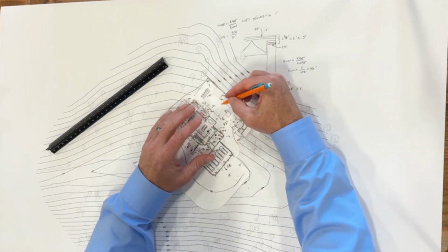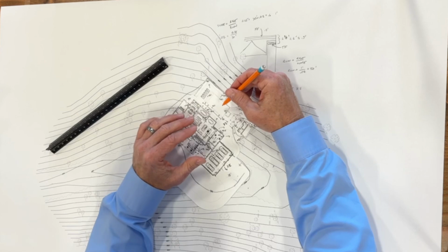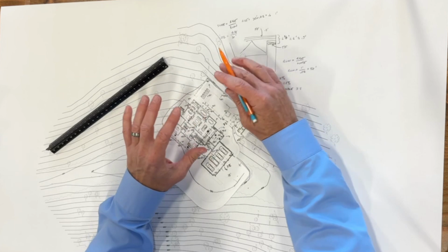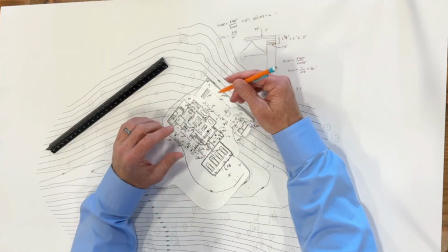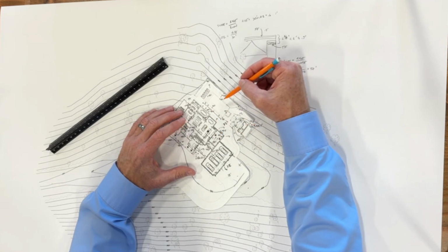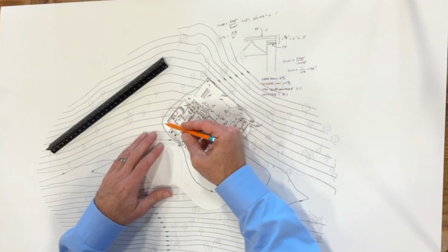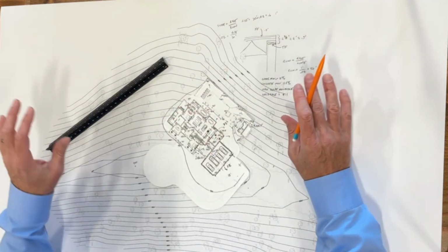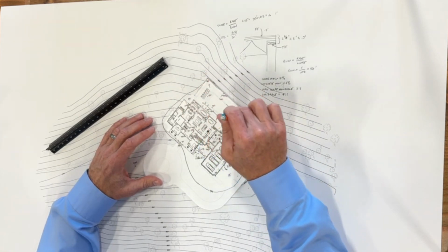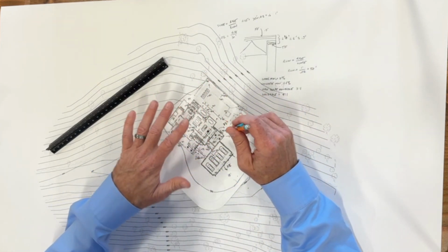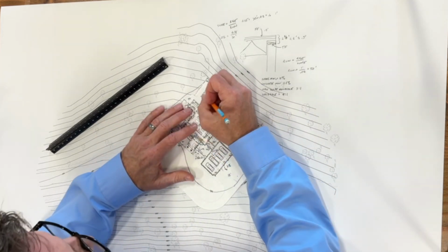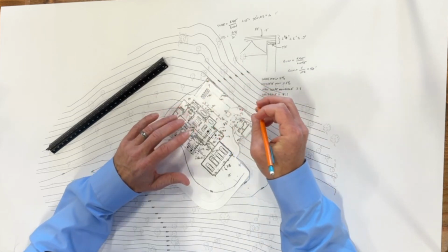Now, notice how flat this is, right? If this is not done correctly and we don't allow for all these little 6-inch drops, there will be water hanging in all these places. So it is actually harder to do this spot where it's flat, because you've got to make sure that drainage is always working. This is way harder than anything over here, because this is just going to shed off like crazy. But every drop of water now will be going more than a 2% slope. Now, we just kind of winged this, and I'd like to double check all the spots. You want to look at where the drop of water is going to go. By the way, yeah, that drains a 940.5.